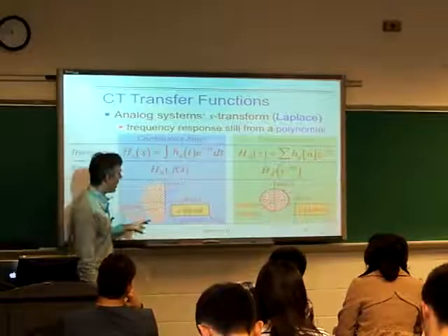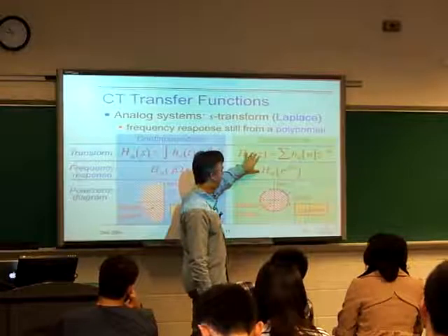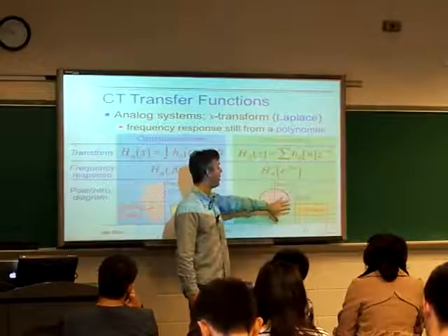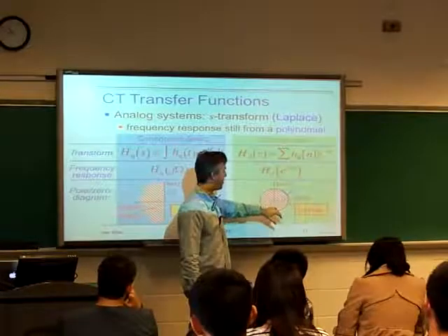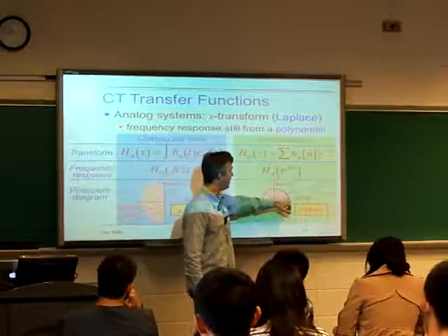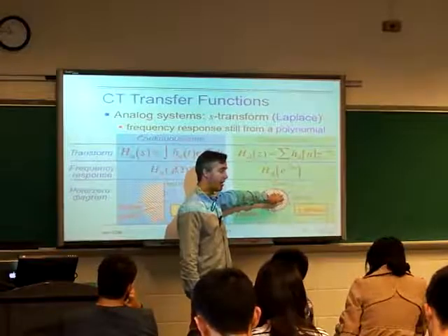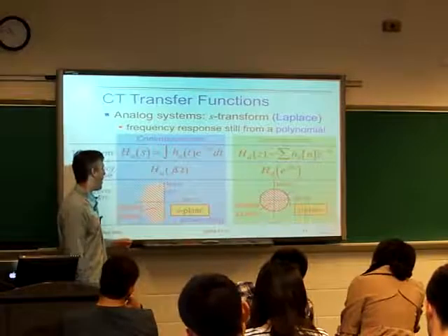So that means we can think, again, in the same way that we understood the z transform, the z polynomial, as a function over the z plane, right? It's a function that can be evaluated for all values of z, and then we had special interpretations of different parts of the z plane. The unit circle as the frequency response, and then wanting poles to be on the inside of the unit circle for a stable system. We have the same thing with the S plane.